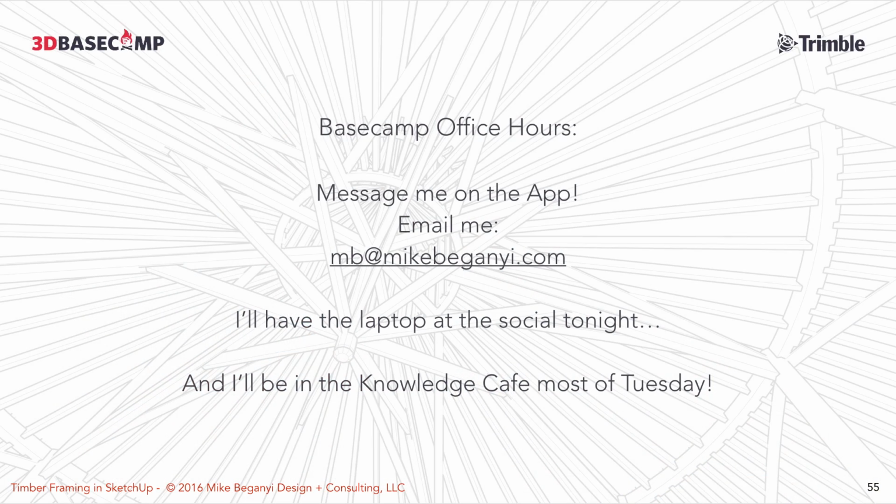Occasionally I'll get stuff from architects, and there's just so much stuff in there that SketchUp will choke on the import, and I don't want to go clean it up. So I'll actually open it in DraftSite, and I'll delete all the stuff, all the hatches, all the weird line weights. That's another piece of software that I just discovered about a year ago, and I'll do that to bring it in before I clean things up.